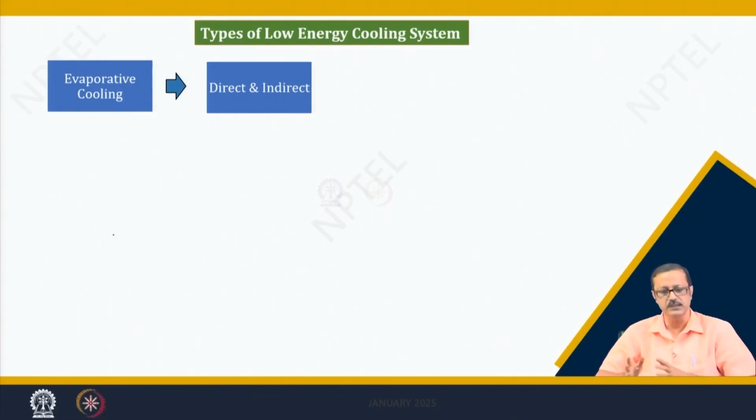Evaporative cooling is, as you understand, the green axis of what we discussed in the last slide, and by virtue of the evaporation we increase the humidity ratio, we decrease the sensible heat of a particular mass of air, and we can feel better, but definitely that system can be adopted in a hot and dry climate.